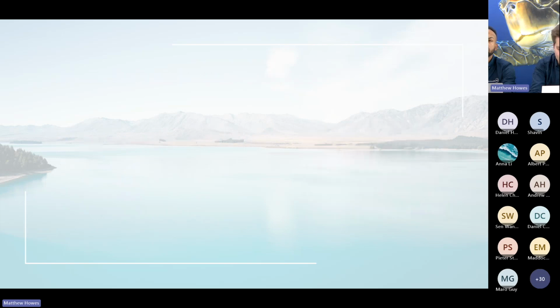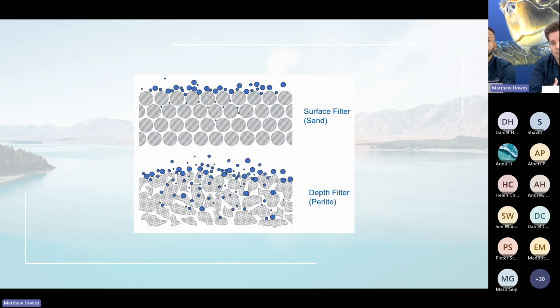One of the absolute key things with the StormFilter, and especially the use of perlite, is that perlite itself is a depth filter, and we covered this in quite a lot of detail in the previous webinar. With a sand filter, most of the contaminants stay at the surface. Whereas with perlite, both within the media itself and between the media particles, the sediment gets absorbed all the way through. You'll see in some photos coming up that the sediment doesn't sit solely at the edge of the cartridge, it's all the way through. Perlite is a depth filter.